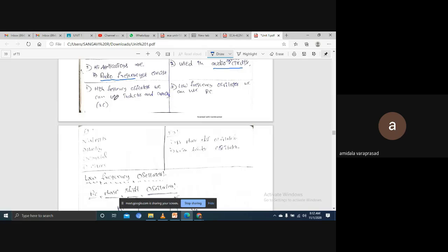High frequency oscillators use LC circuits, inductor and capacitor, in the feedback network. Low frequency oscillators use RC, resistor and capacitor, in the feedback network. Examples of the high frequency type are the Colpitts, Hartley, Crystal, and Clapp oscillators. Examples of the low frequency type are the RC phase shift oscillator and the Wien Bridge oscillator.